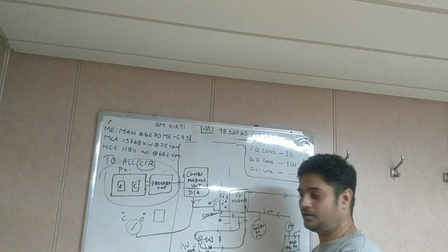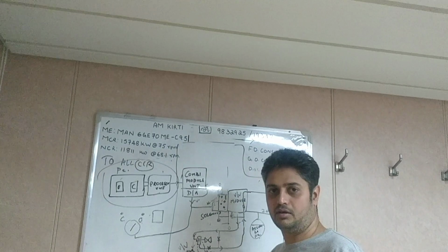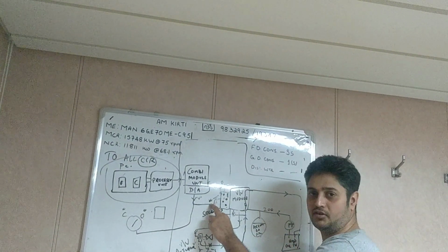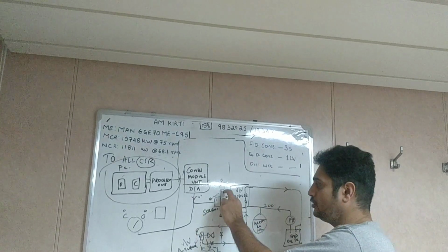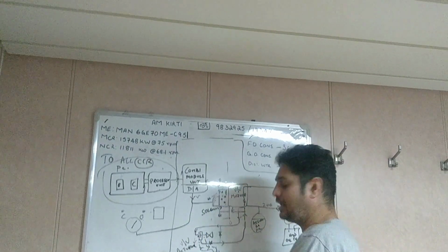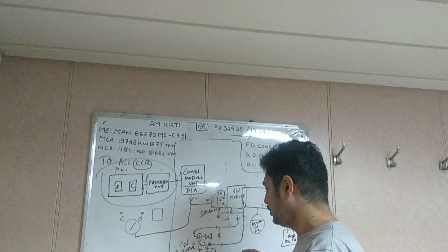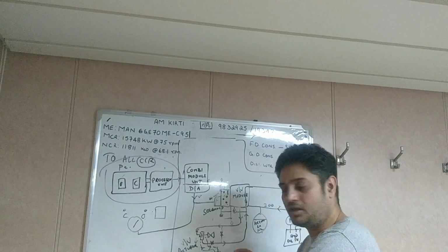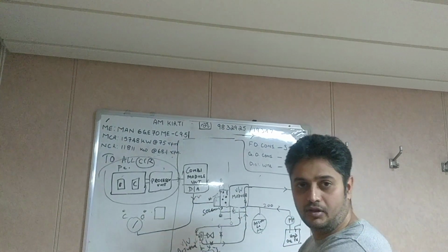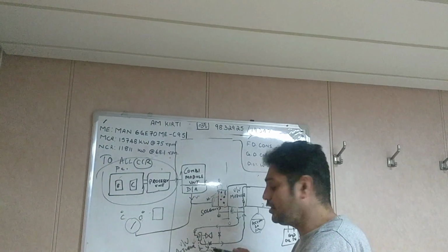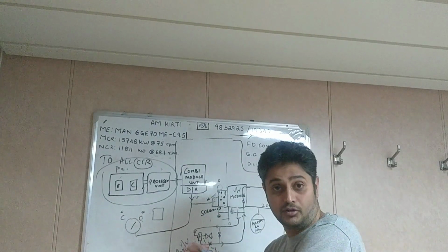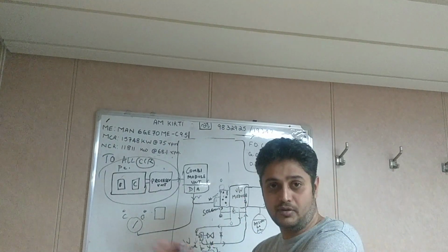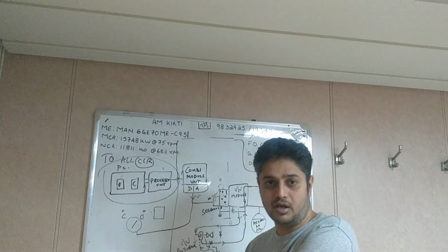If here everything is okay but it is not moving, even after the hydraulic pump, then you can do another way of troubleshooting. Another problem you can face is that the solenoid is getting energized, you are pushing this also, but still the valve is not able to move. Then you try with the emergency pump, and still the valve is not able to move, which means you need to overhaul the valve. Otherwise you need to overhaul the actuator also. If the actuator is stuck, immediately don't go for the valve, first get the actuator overhauled. Maybe it would have been stuck.